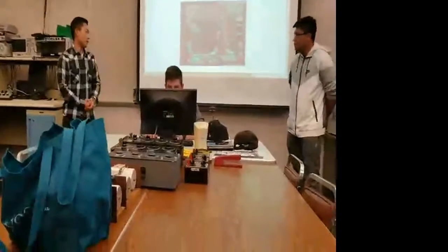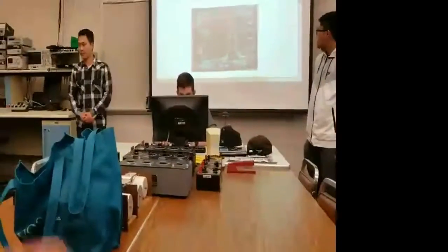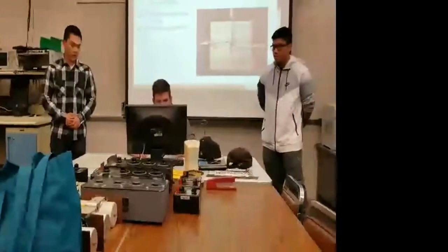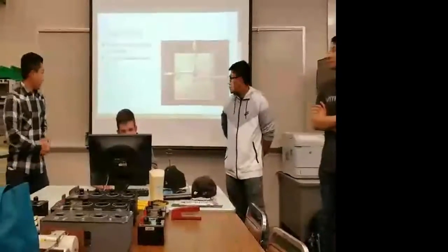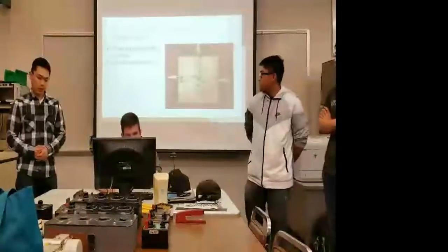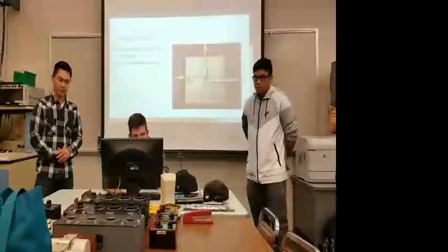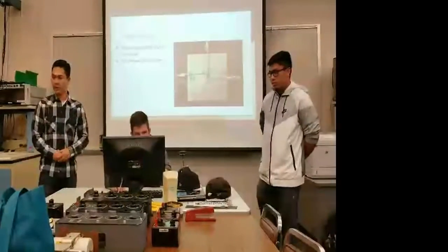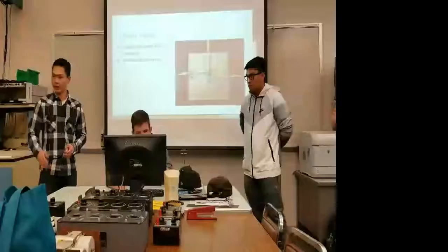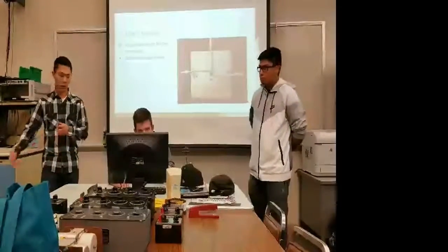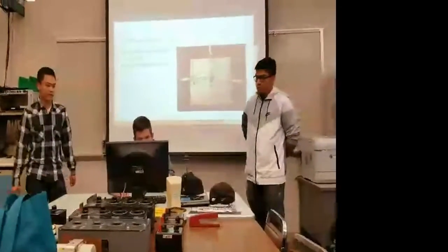And it's just a capture of our testing of the mixer. So these are the few issues that were there with the mixers. It's just really being careful with that air gap being produced when connecting those coaxes to the mixer itself.